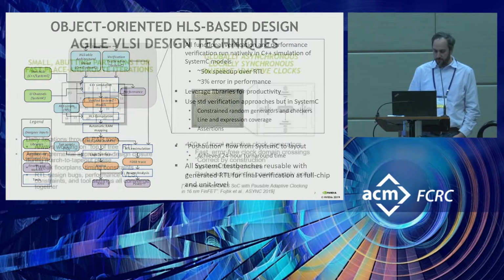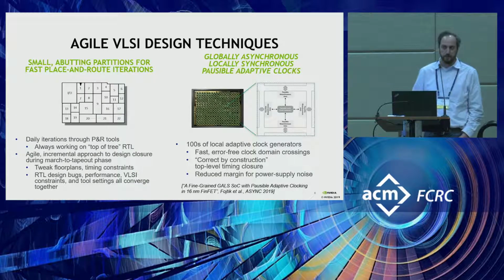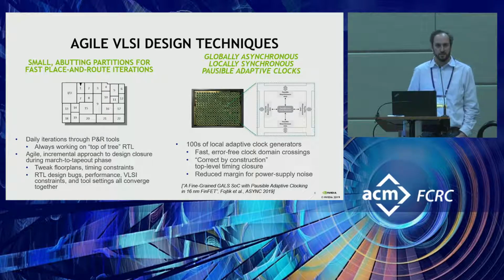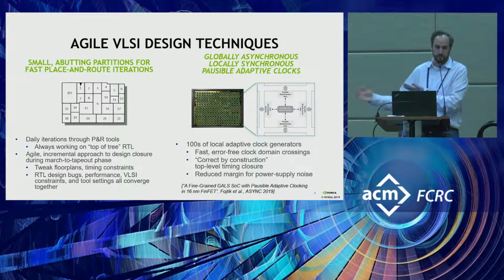Right, so the other thing that we've done is say, okay, let's say that problem is solved. If I was able to iterate on my C model for my design, fixing bugs every few hours or every day, but then it took me a week to push through the tools, it wouldn't be a very agile flow. So the goal we had in mind is that we fix bugs, run all the way through the layout flow, and then be able to look at the results the next day.